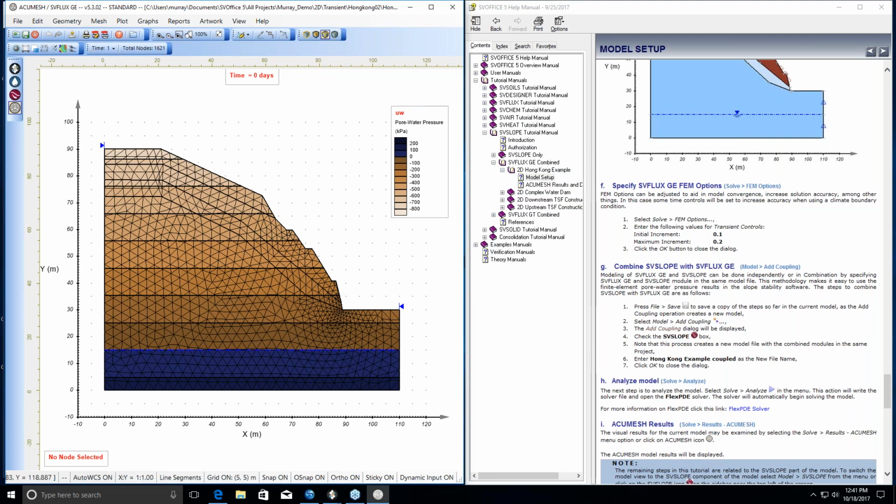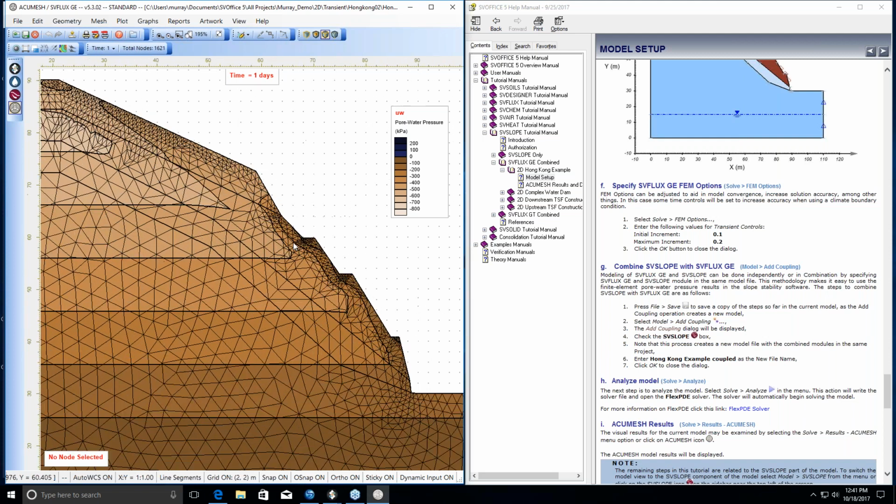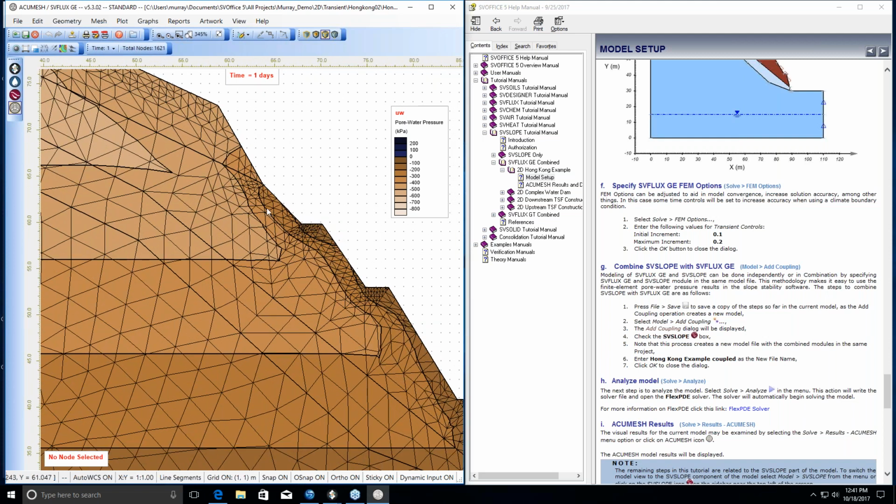And if you look here, what's interesting is time 1, which is right after the first rainfall event has happened. You can see that the rainfall has been applied to the boundary, and what's nice is you're seeing automatic mesh refinement kick in along the boundary to improve the quality of your solution, because this is where the action is taking place in the model.